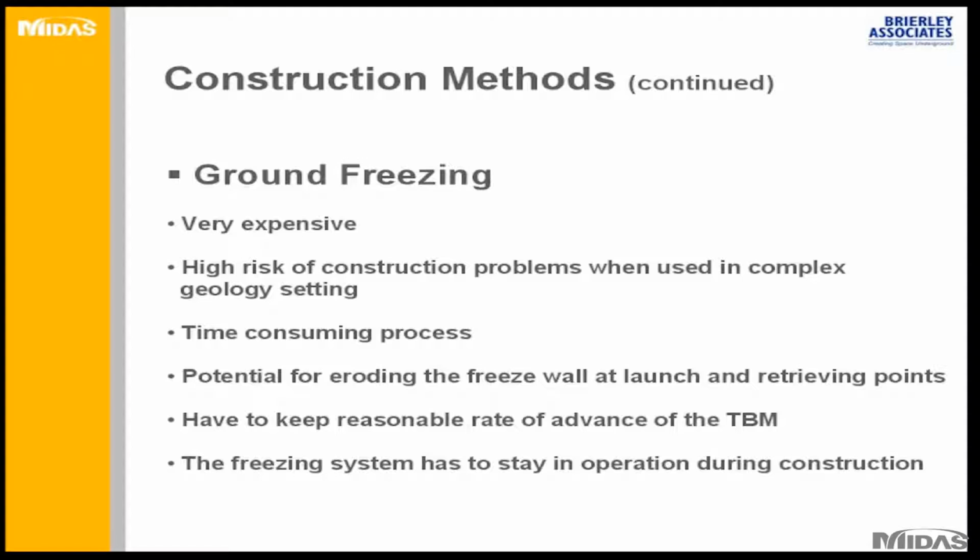The other issue is you should always keep a reasonable rate of advance of the TBM during the course of the project, especially near the shaft itself. There was one case history where the TBM broke shortly after the breakthrough near the shaft, and it took 3 days to fix the TBM. When the contractor tried to advance the TBM, he couldn't, and the TBM was actually frozen in place.